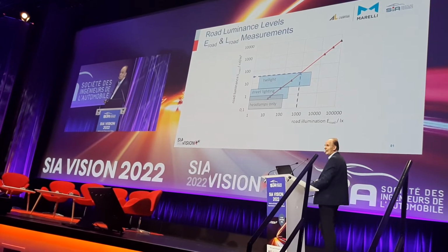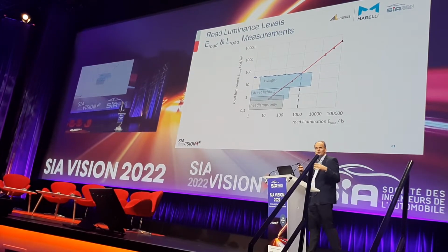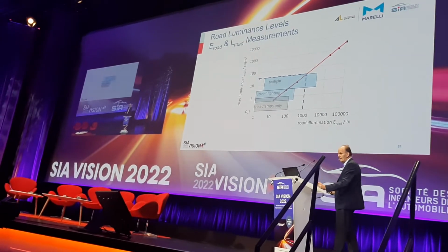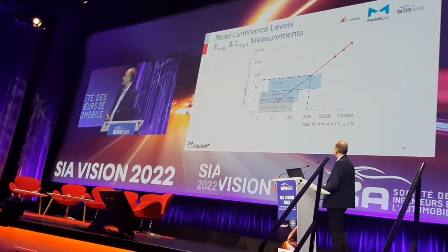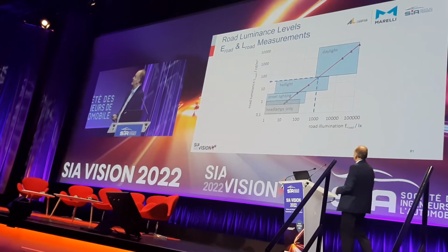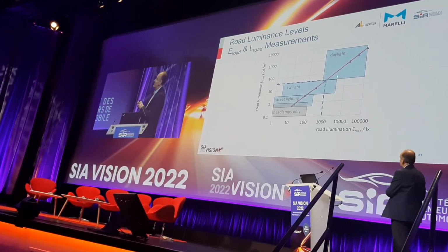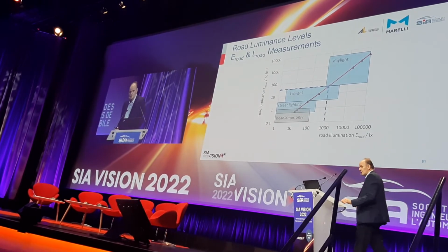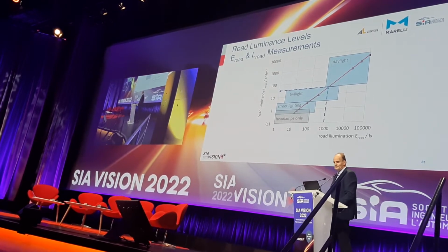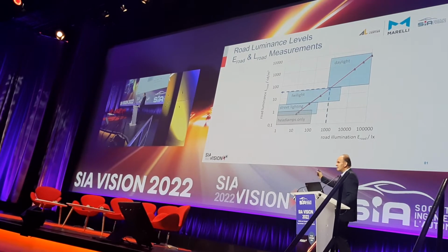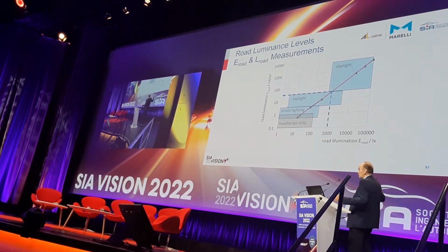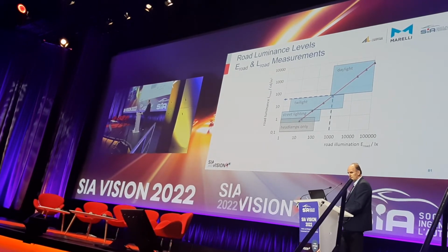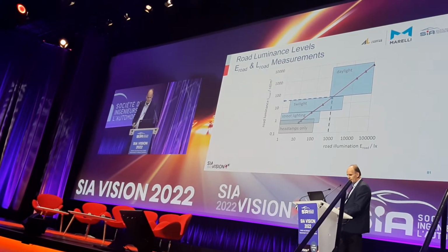Then there is the twilight area, where the question is low beam switched on or DRL. I will show a small statistic about this later on. And then we have the daytime area, with the cloudy sky and with the bright sunshine at 100,000 lux on the road. All this large spread of illumination and luminance we have to take into account for controlling our lighting functions.